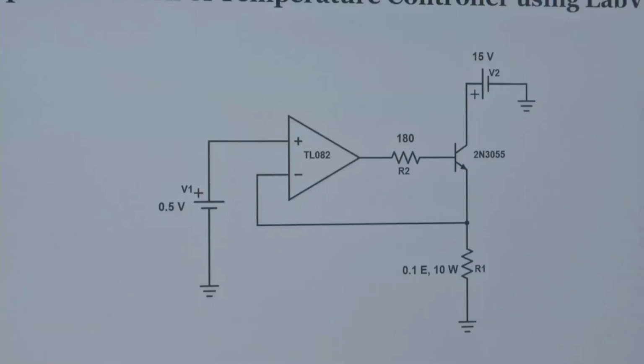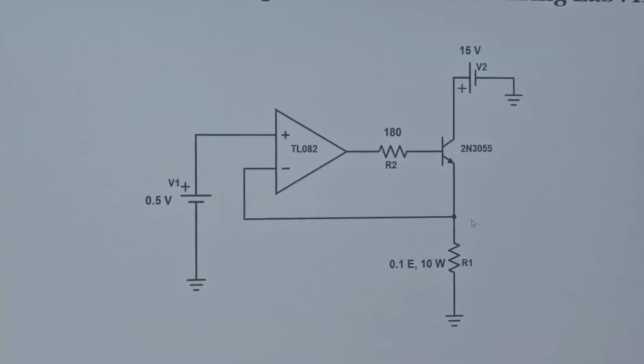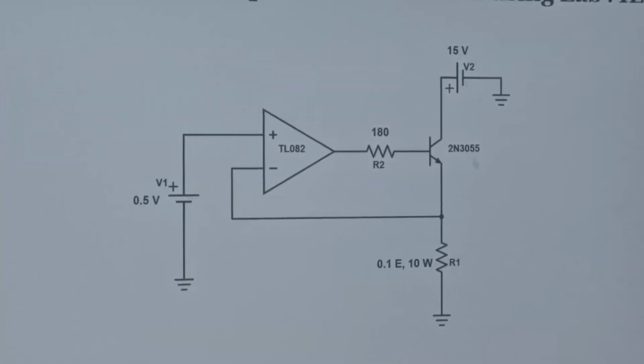But you may ask how exactly this is going to generate temperature on top of a transistor. So, in this case I am generating temperature on top of a transistor. How? If I do not have this negative feedback, it is not in a forced condition. Whatever voltage you apply, the complete voltage will be dropped across this resistance, and the drop across collector and emitter will be 0.7 in a normal case without negative feedback. But in this case you have negative feedback. Because of it, the voltage drop across this resistor is forced to be 0.5, and the input voltage applied is 15 volts.